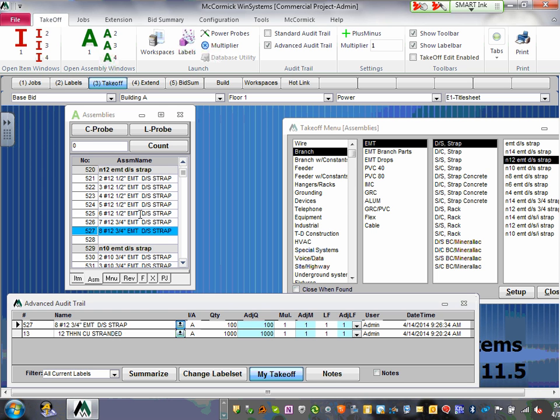You put it in the ceiling, and you bring the conduit to it, and then you can pull as many conductors in any direction as you want. So don't limit yourself with smaller boxes where you have fill issues and what's not. You have a deep 4 11/16 box, put it in the ceiling, bring to it 3/4 of an inch with 6 circuits like we did, and you still have plenty of room for other circuits too. Remember, a 3/4 of an inch conduit, guys, can carry 16 conductors. If you load it with 8, you still have how much extra for future use?